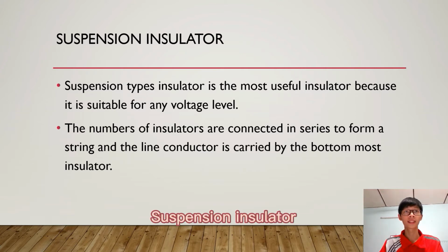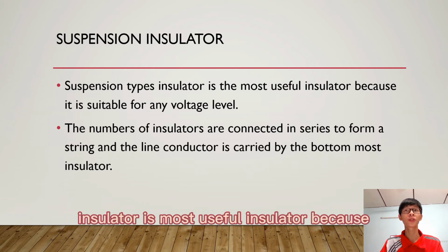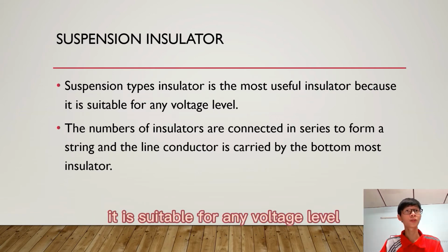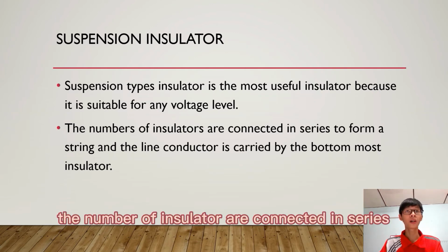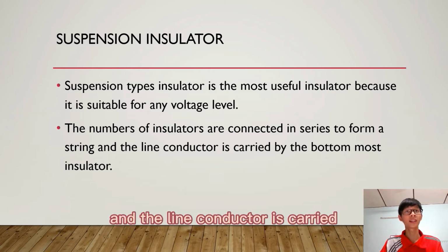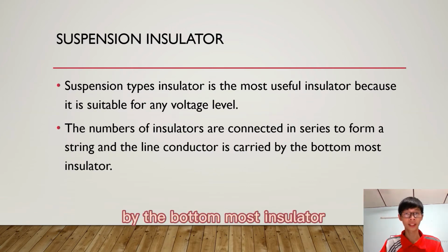Suspension insulator. Suspension type insulator is the most useful insulator because it is suitable for any voltage level. After that, a number of insulators are connected in series to form a string and the line conductor is carried by the bottommost insulator.